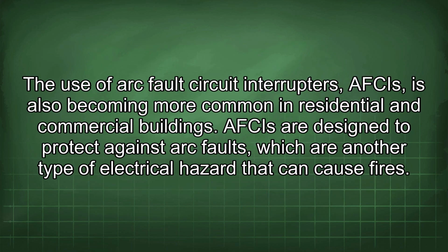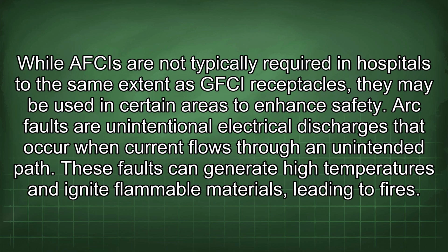The use of arc fault circuit interrupters (AFCIs) is also becoming more common in residential and commercial buildings. AFCIs are designed to protect against arc faults, which are another type of electrical hazard that can cause fires. While AFCIs are not typically required in hospitals to the same extent as GFCI receptacles, they may be used in certain areas to enhance safety.